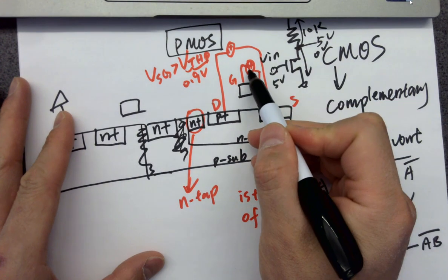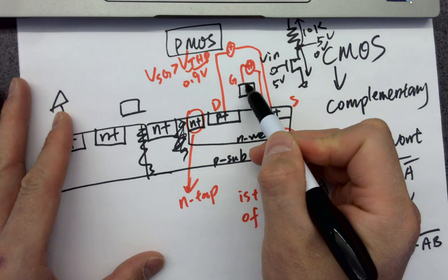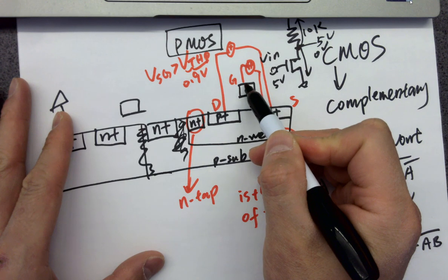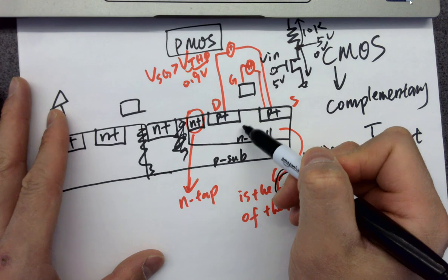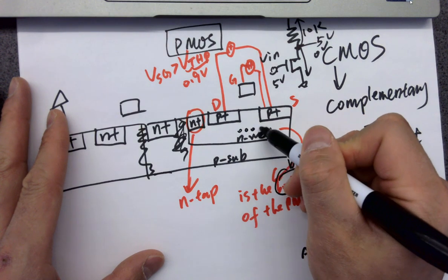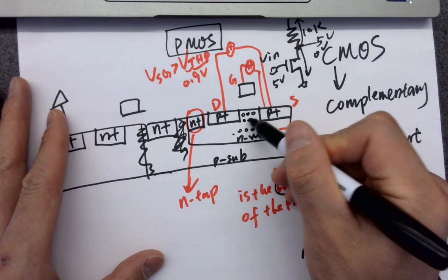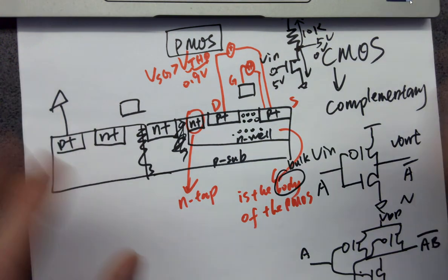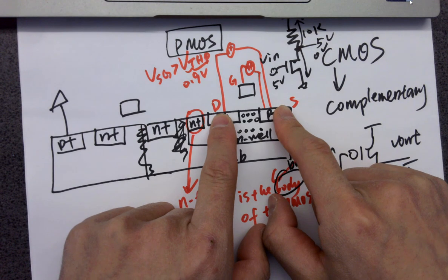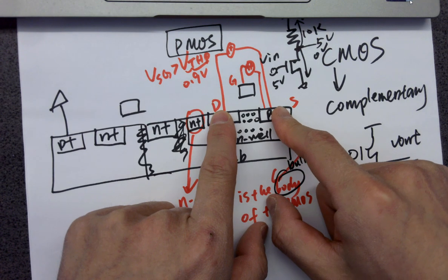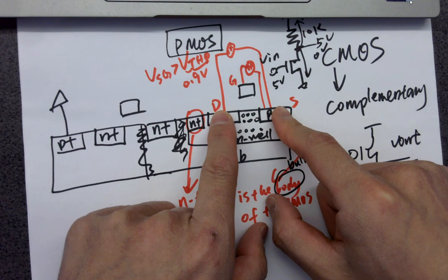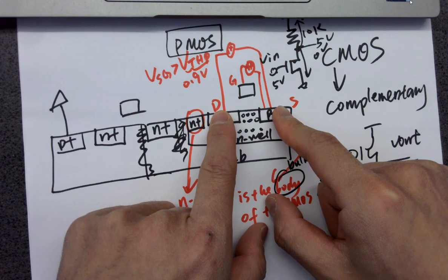Because you can see this negative voltage here, the cathode of the battery is applied to the gate instead of an anode. So you can imagine this electric field will attract holes into the channel. There are holes here being attracted. And then I apply a potential difference between source and drain, higher and lower. So what's going to happen? What's physically happening here?